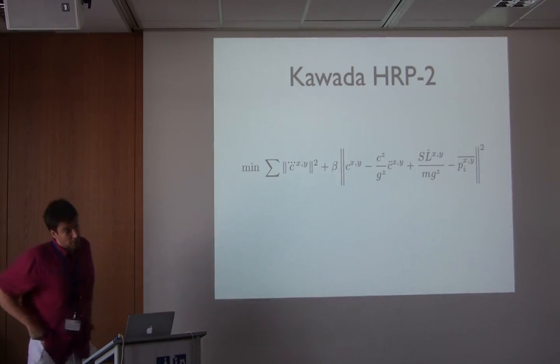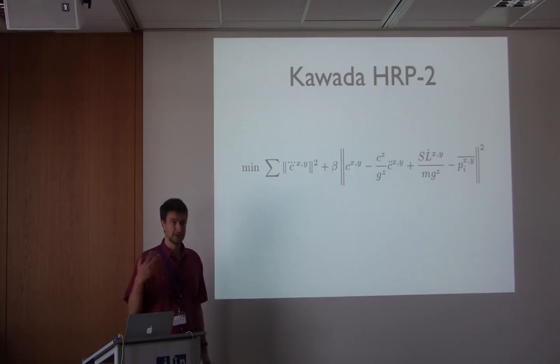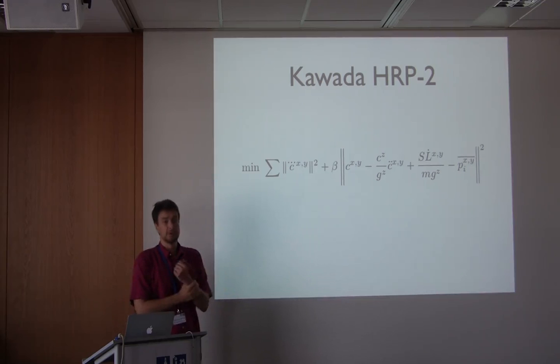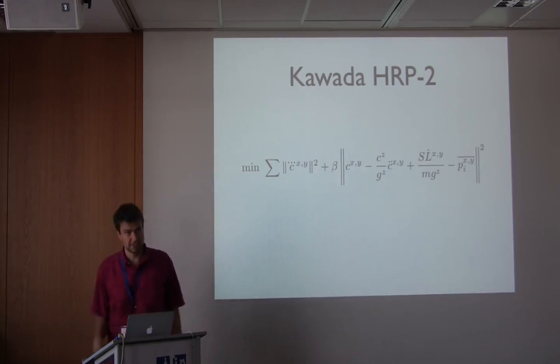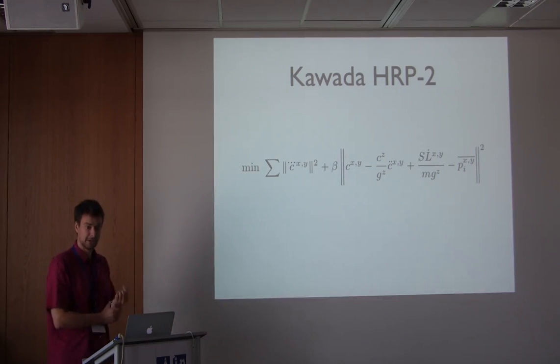Moreover, of course, you can see from your knowledge of linear dynamics that the higher derivative will diverge more quickly. So the higher derivative you consider, the faster you can react to instabilities. Now, of course, the higher derivative also means the more noisy your system is. So he chose the third derivative. That's it. And you can choose something else. I will show you that I choose something else